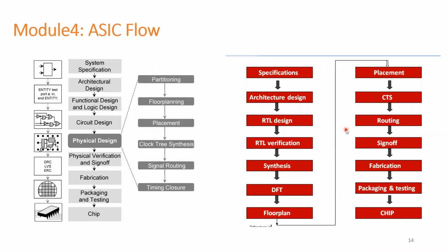In PDN team, they will analyze the static timing and static IR drop and dynamic IR drop. If there are any violations in static timing, static IR drop and dynamic IR drop, they will report it back to physical design engineers. Also, the PDN team will check for signal EM, power EM. If there are any power EM and signal EM, that also we need to fix.